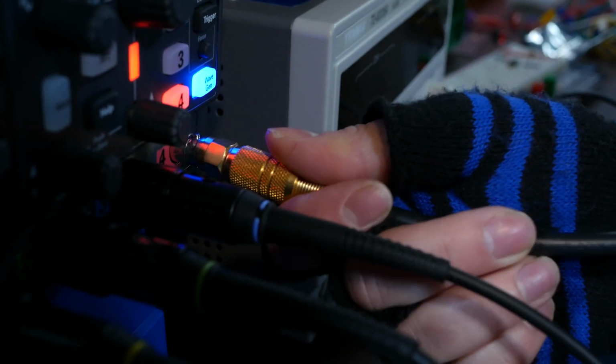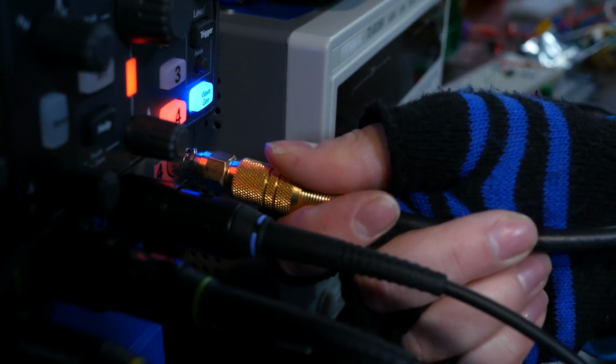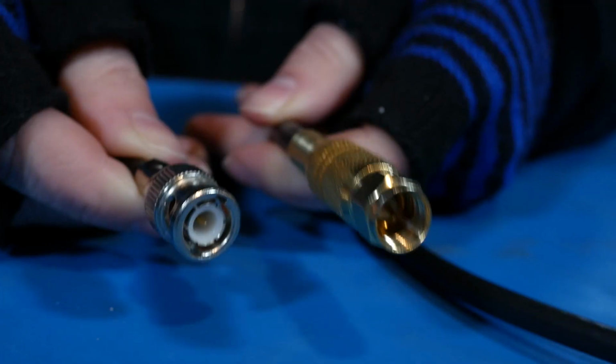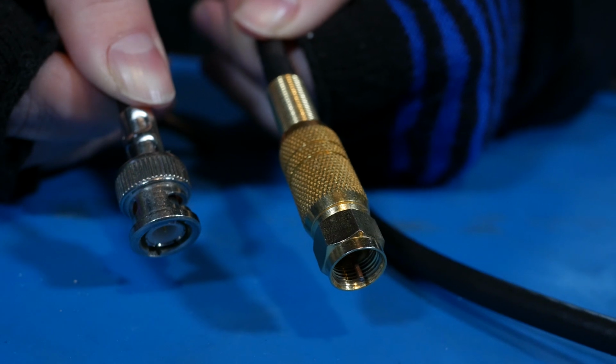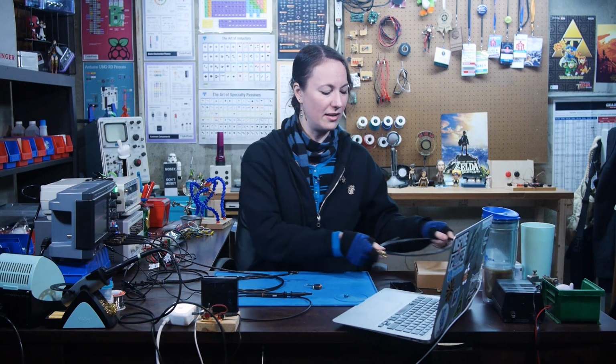So William was trying to walk me through making one of these probes and said, just grab some coax cable you've got lying around. So I'm like, yeah, I used to use bunny ears. I'll grab one. And so I cut my cable in half and I was going to start making it. And then I realized that, yes, this is not the connector that is on my oscilloscope. So if you're going to make one of these, make sure that you either have an adapter or that the cable you use has the correct connector to connect to your scope.